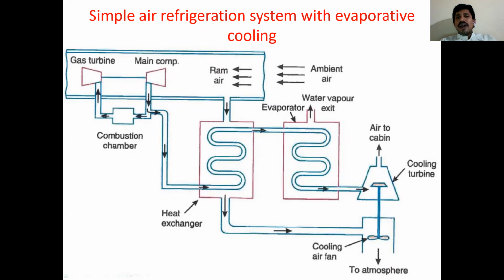See, atmospheric air first of all enters the diffuser, in which the ramming process takes place. Due to this ramming process, the atmospheric air pressure increases to a certain level. So the pressure value increases, and after this you will have the stagnation temperature after the ramming process. So we reach here, see the cursor.